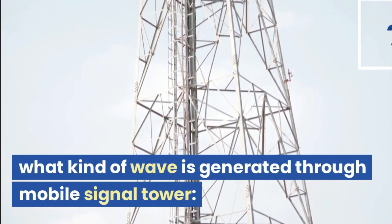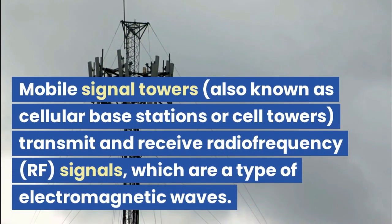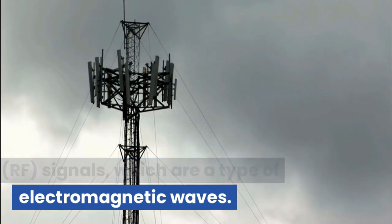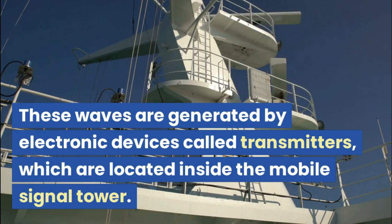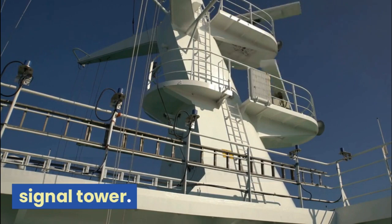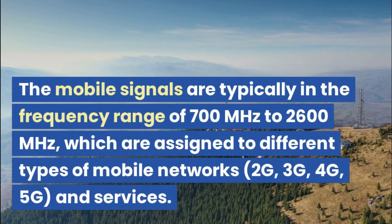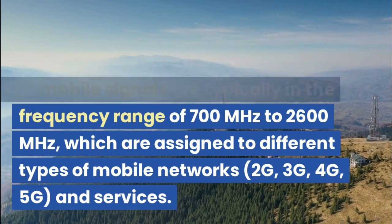What kind of wave is generated through mobile signal tower? Mobile signal towers, also known as cellular base stations or cell towers, transmit and receive radio frequency (RF) signals, which are a type of electromagnetic waves. These waves are generated by electronic devices called transmitters, which are located inside the mobile signal tower. The mobile signals are typically in the frequency range of 700 MHz to 2600 MHz, which are assigned to different types of mobile networks: 2G, 3G, 4G, 5G, and services.